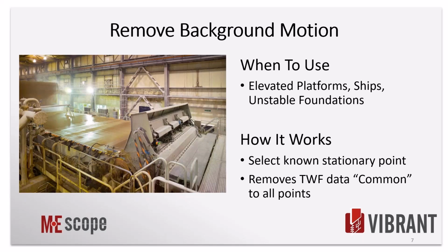Even if you're using accelerometers in a traditional sense, say we want to focus strictly on the vibration of the machine and not on the vibration of the platform, because obviously the two of those are going to be combined, the only way you could really do that would be by putting an accelerometer on the platform itself, measuring that data as well, and then taking those time waveforms from that accelerometer and removing them from the machine, or from the structure as well. This is the equivalent of that.